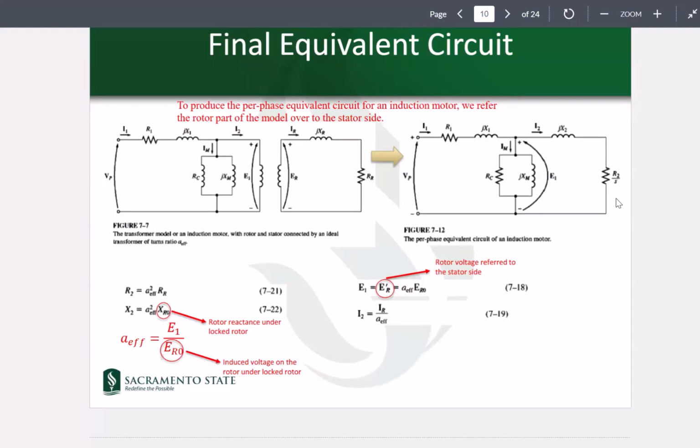That E1 doesn't change with voltage. It changes with voltage, but only to a small extent, because these two impedances are one next to another. So basically nothing is dependent on the frequency in here, not even on X2. The only part that changes with the changes of slip and the frequency on the rotor would be now R2 over S. Now, these are basically the equivalent representations.